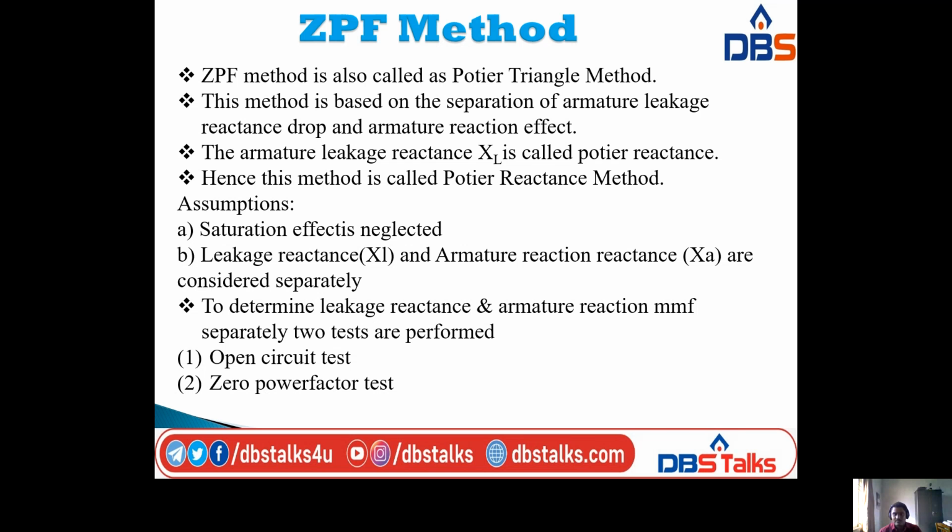Next, we will consider some assumptions, similar to the previous two methods, that is the EMF and MMF methods. Here also I am taking assumptions. Here also the saturation effect is neglected. And the second assumption is that leakage reactance XL and armature reaction reactance XA are considered separately. This is the main case we are using here. This method is based on the separation of armature leakage reactance drop